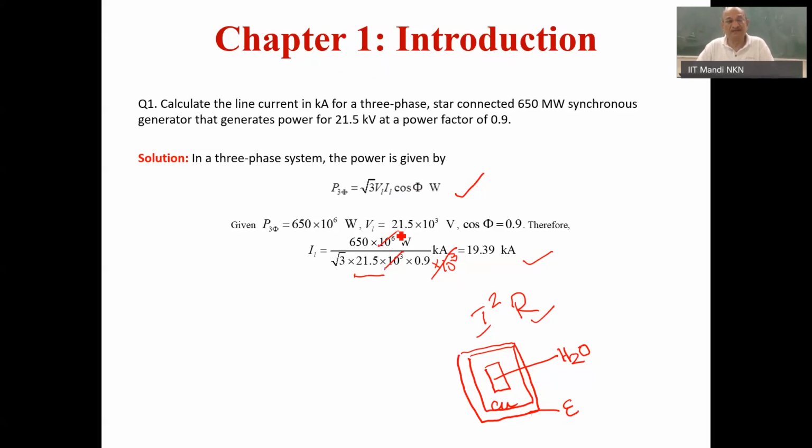And for taped insulation, there is a limit to the voltage it can withstand, because when you provide insulation by layers of tape above each other, there will always be air pockets in between.